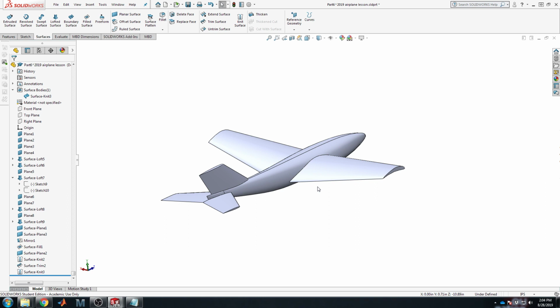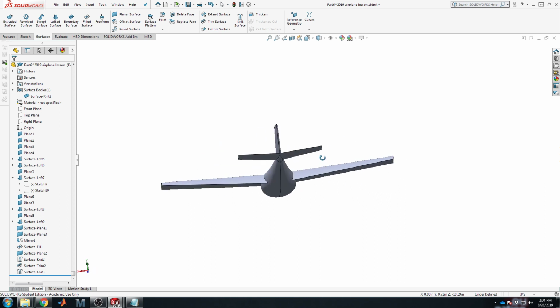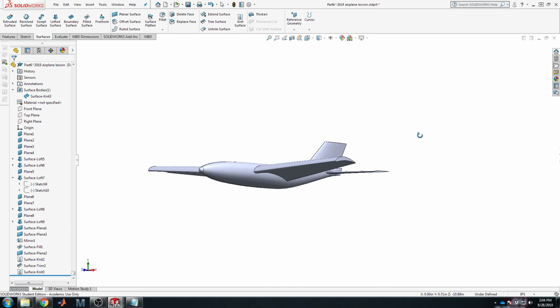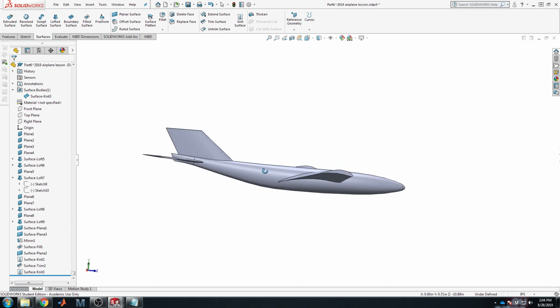Once we start adding blends between the wing and the fuselage, the ease and simplicity of that goes away a lot. So enjoy this simplicity while it exists, and don't go into blending everything until you're ready to commit to a particular OML shape.